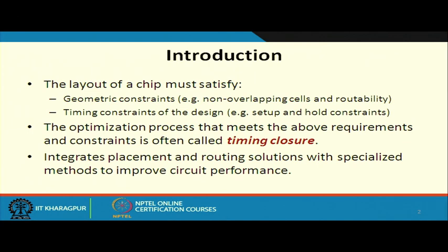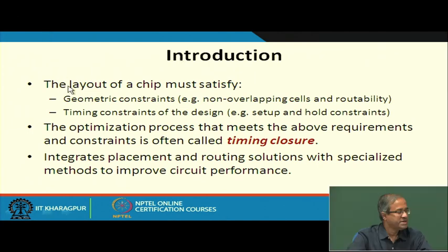So, you see, when the layout of a chip is created, it is through the entire back end design process. So, from the netlist that we get from the front end design, we can do some circuit partitioning, then possibly floor planning and placement, routing, and then the final layout, right.